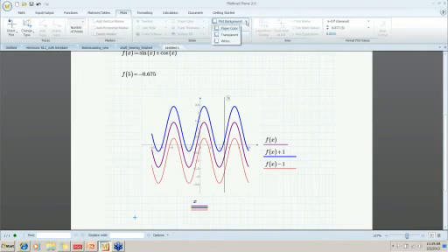There's something called plot background. We have the engineering paper here, which is very faint, but it's there, and it's set to the regular size mesh. When you have a plot, that engineering paper by default gets blocked out within your plot. If you want to display it, you set that setting here. You could have the background of your plot be white, it could be the color of the paper, or it could be transparent. So that's a little bit about 2D plotting.